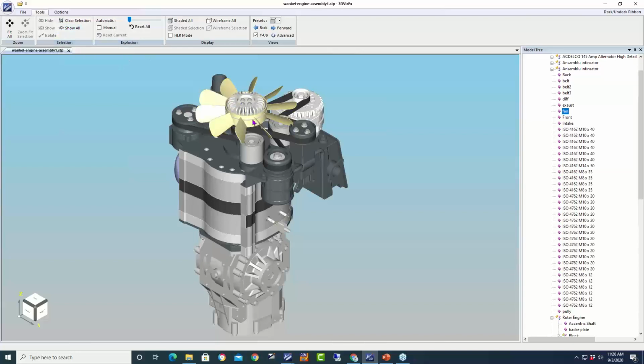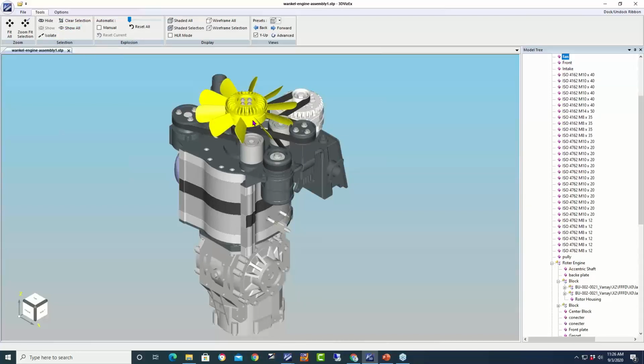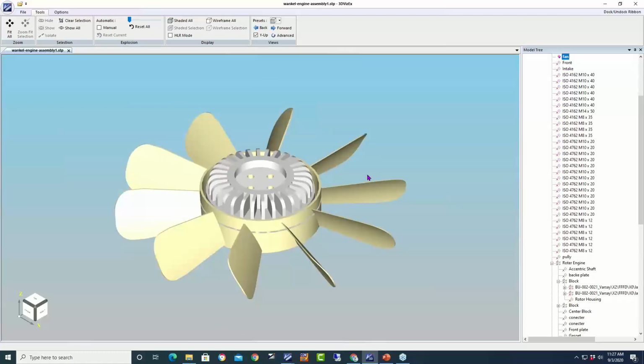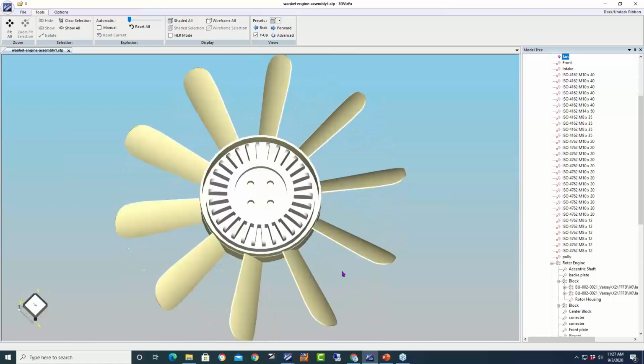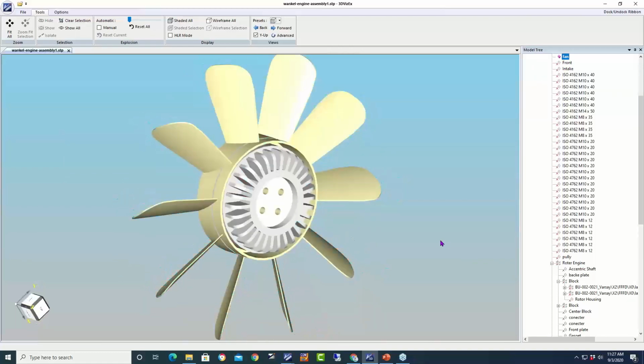One of the other things I can do is just click on the part and I can isolate it. So you can see we've got the isolate thing here. If I want to work with one particular assembly or sub-assembly, I can say isolate, and that just brings this onto its own window. And I can just work with that particular part. And you'll see on the right, virtually everything now has a cross by it, which shows I'm not actually viewing it anymore. So the whole model is still here. I've not got rid of it. It's just hidden.